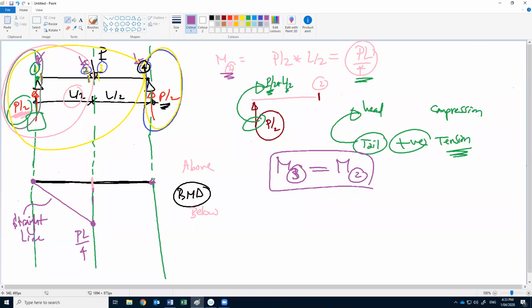How to connect between 3 and 4? How to connect between this point and this point? It could be a straight line, as well, because we don't have any forces. So this is how to deal with the moment. We calculate at our sections or cuts we defined before, then connect these values with straight lines, because we don't have any forces between them.